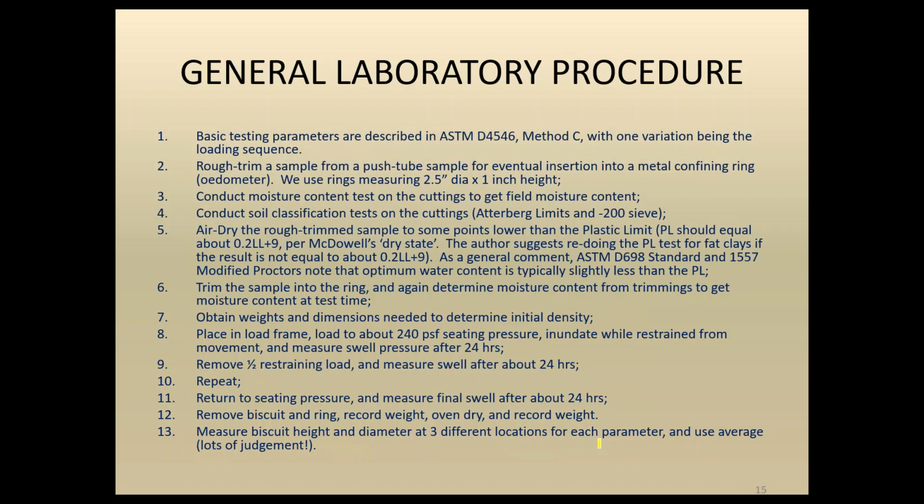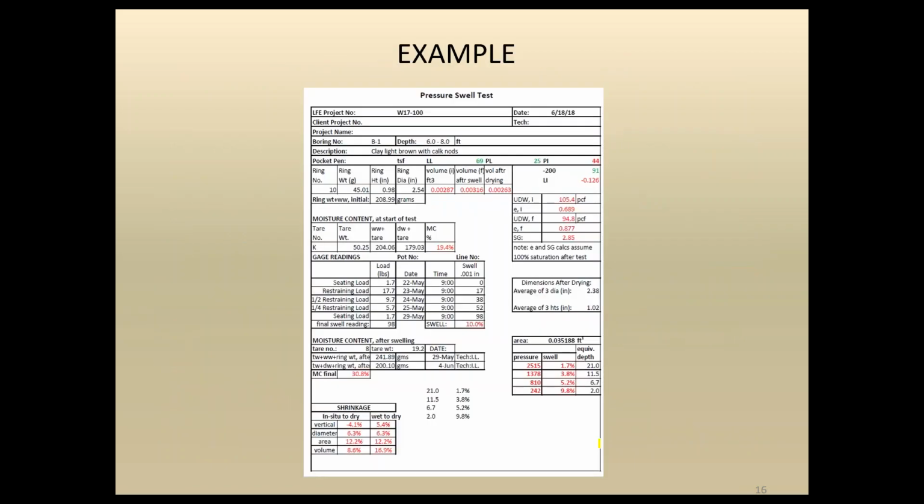And so just taking a look at and measuring the dimensions after it's dried back, you would expect to measure considerable shrinkage. That would show that you wouldn't necessarily be reporting that this sample with a PI of 50 did not have swell. It actually indicates the test might not have been correctly done, and those shrinkage measurements would show that considerable shrinkage was measured, indicating that it should have also had considerable swell potential.